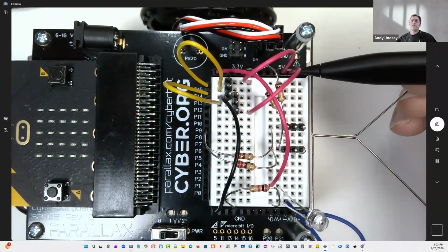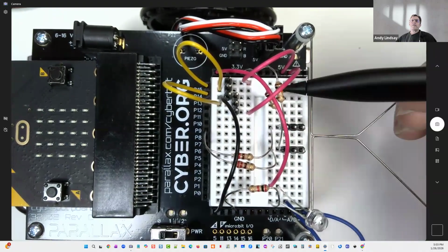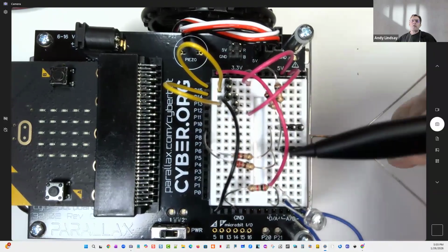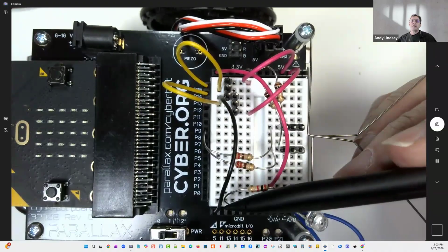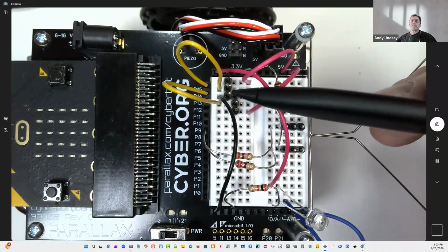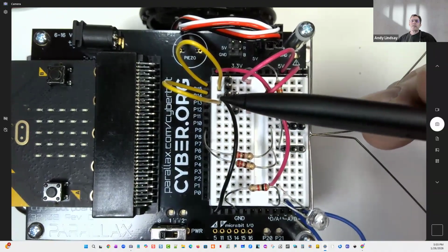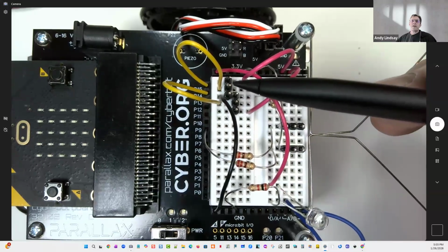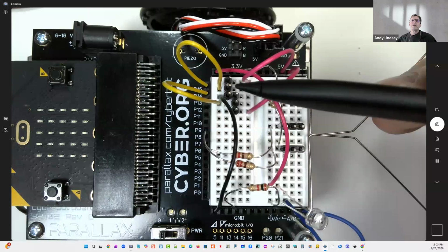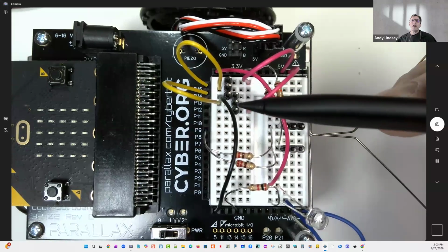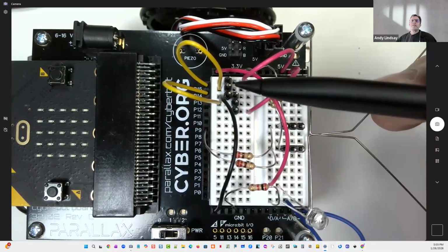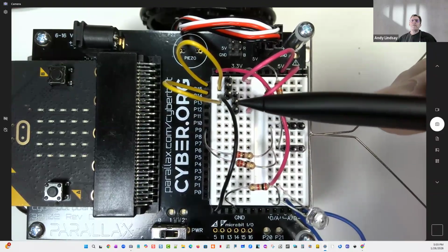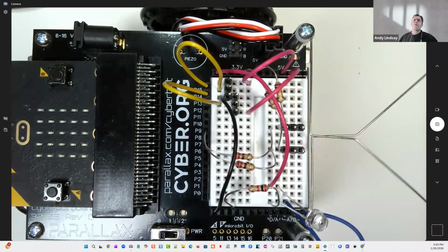Okay, so what we're going to do again is the top and bottom pins go to 5 volts, the 5V sockets. The pair of middle pins will get a wire that goes to ground, GND. So that's the middle pins that are shorted together on a single row. Then the middle pins of the 3-pin headers, so that's the second row and the fourth row. The second row pin will get jumpered to P15, and the fourth row pin will get jumpered to P14.